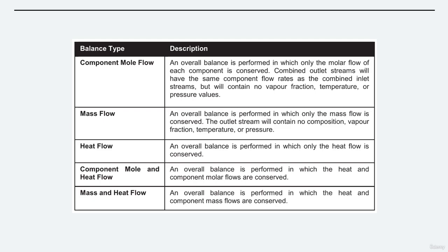The fourth type is component mole and heat flow. That's an overall balance in which the heat and component molar flows are conserved. The last type is mass and heat flow. That's an overall balance in which the heat and component mass flows are conserved.